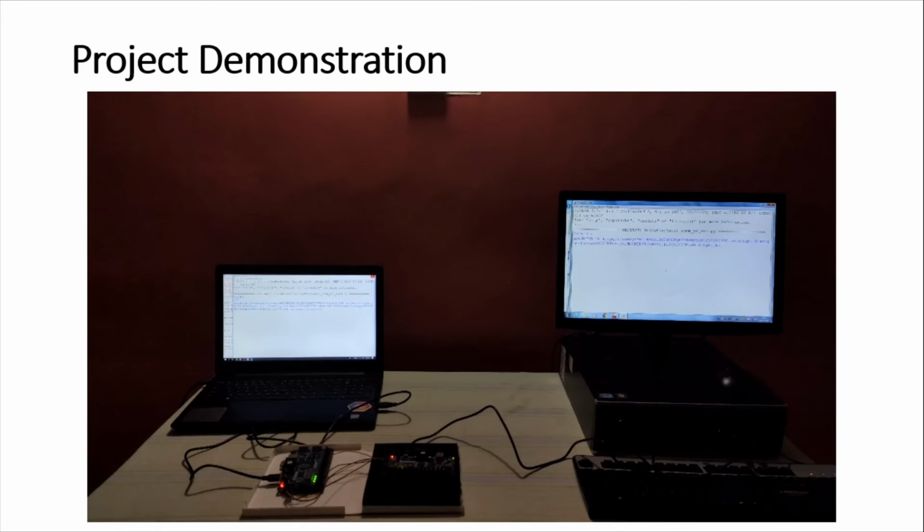512 bytes of data stream is sent from the PC to the transmitter FPGA device, and it does the processing of the data and transmits those to the receiving FPGA via 2 PMOD UART channels, one for the I channel and the other for the Q channel. Then the receiving FPGA does the processing of the data and sends it to the receiving PC.